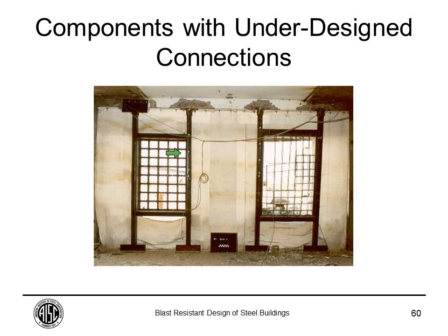In this case, the connections were not properly designed to remain attached to the concrete beam, so it created some sort of concrete breakout failure. Again, that's not desirable because that frame will come out, the whole thing will come out as a system, and fly into the occupied space. We always want to make sure that we remain connected at the connections.